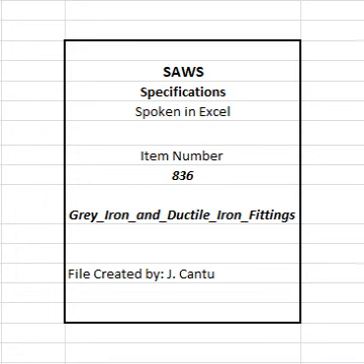Provide lay schedule of pictorial nature indicating alignment and grade, laying dimensions, fitting, flange, and special details, with plan view of each pipe segment sketched, detailing pipe invert elevations, horizontal bends, restraint joints, and other critical features. C. Indicate station numbers for pipe and fittings corresponding to drawings. Do not start production of pipe and fittings prior to review and approval by engineer.